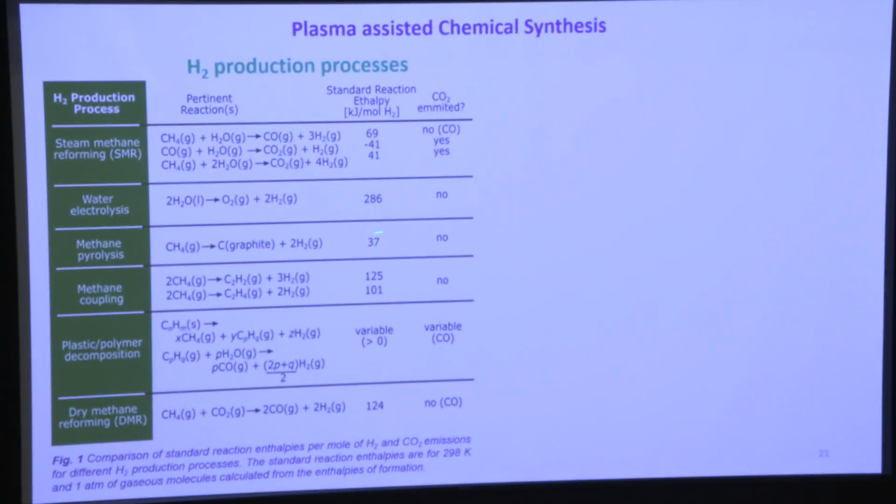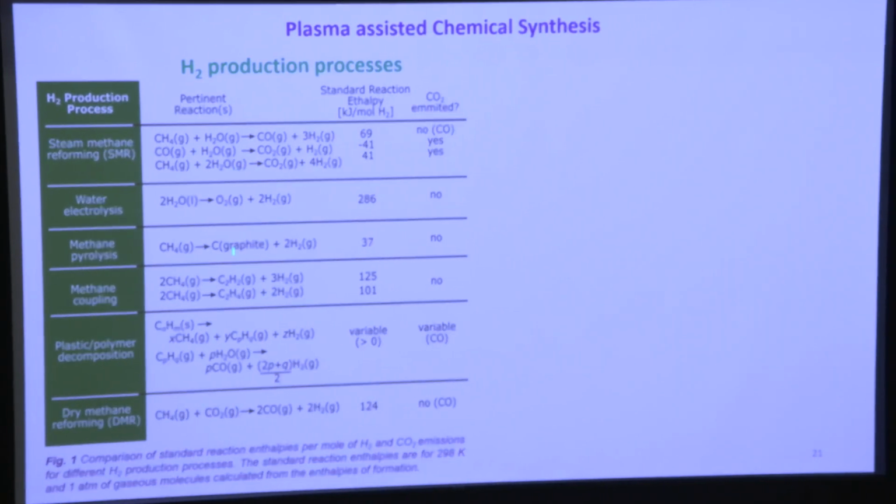You can see that the energy cost in this way is probably 1/8 of the cost of electrolysis. Therefore, methane pyrolysis using plasma, as a form of electrification, might be a viable process before transitioning fully to green energy, particularly for America, because we have a lot of natural gas and petroleum resources. This carbon can be used for battery anode materials and other carbon applications.